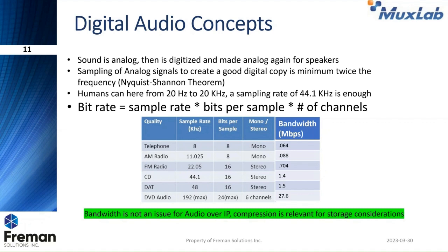However, if we want to put songs inside a device like an iPod, an iPhone, etc., then we compress them because we can put more songs in there. And the way we're going to listen to them with headphones, the quality of the audio is going to be very, very acceptable. As you know, audio over IP was the first thing that we put on the network as AV professionals. We transported audio with EtherSound, with CobraNet, and nowadays with Dante, Q-SYS, AVB, etc. And those applications are the simpler ones to do, simply because audio is a very low bandwidth signal compared to video and compared to what a network can handle.